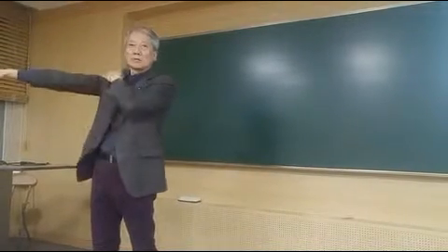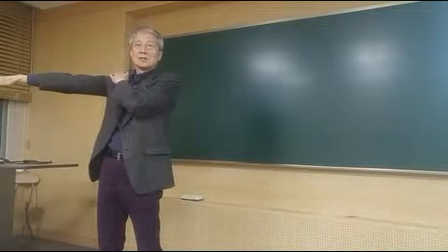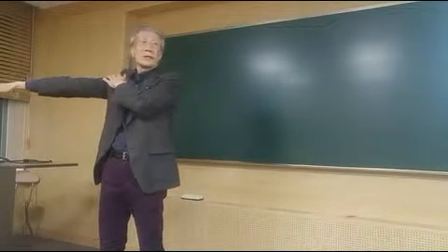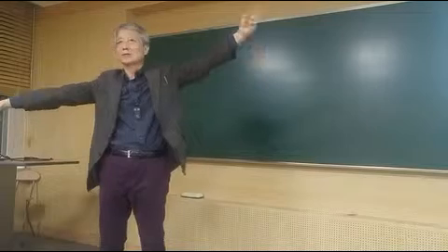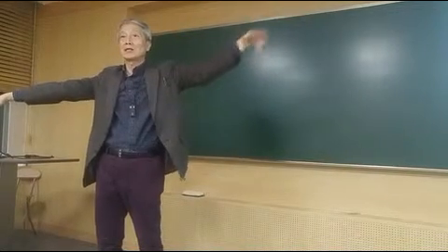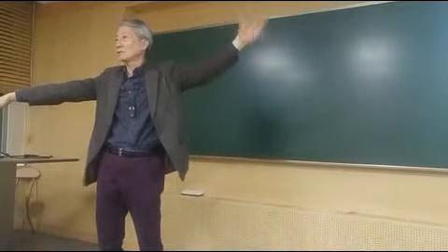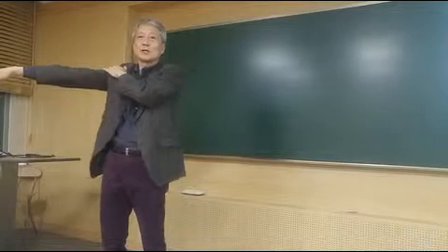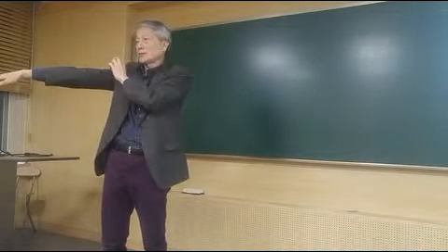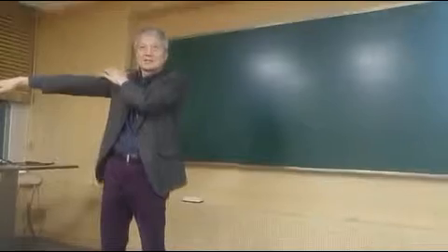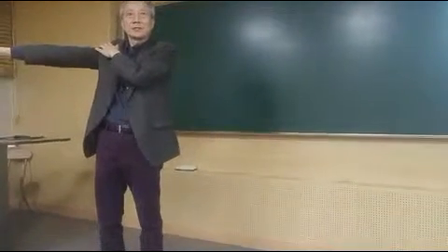So it should be strong here. I found this by simulating the structural strength calculation, the finite element method. So I should increase the thickness of some structural part over here.